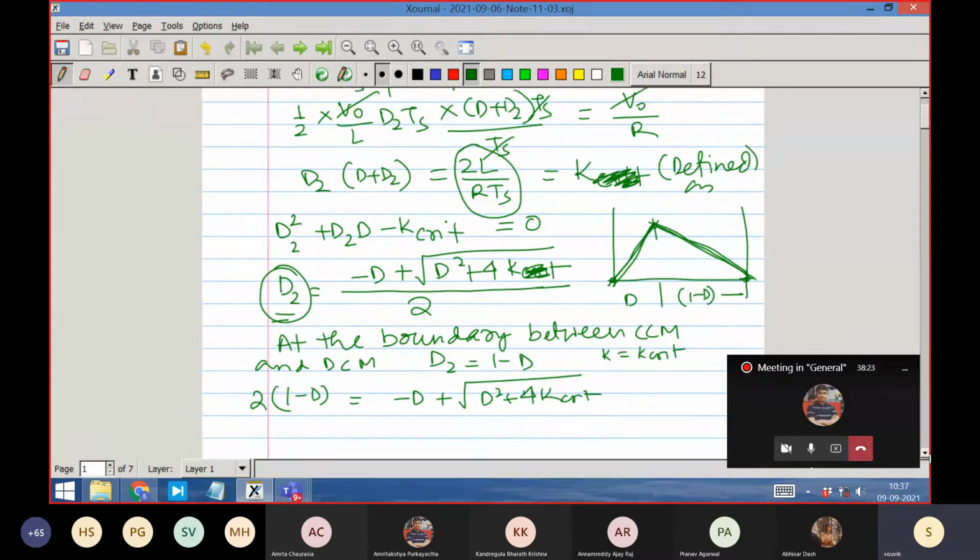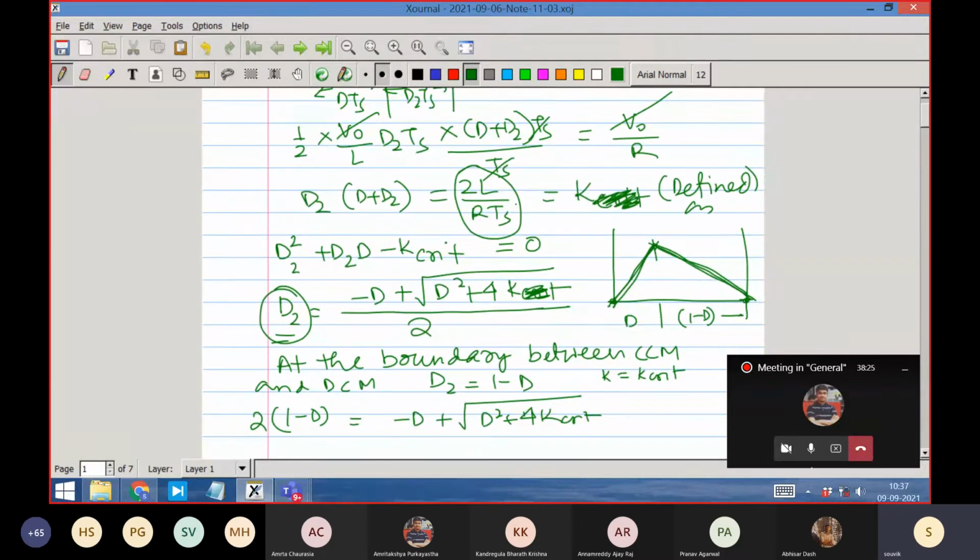I'm slightly confusing you. I just want to define K as the conduction parameter. The word critical I will bring in when there is a critical condition. Critical condition means when K is such a value that it produces a boundary condition for the inductor current, that is, the inductor current is at the boundary between continuous and discontinuous conduction mode.